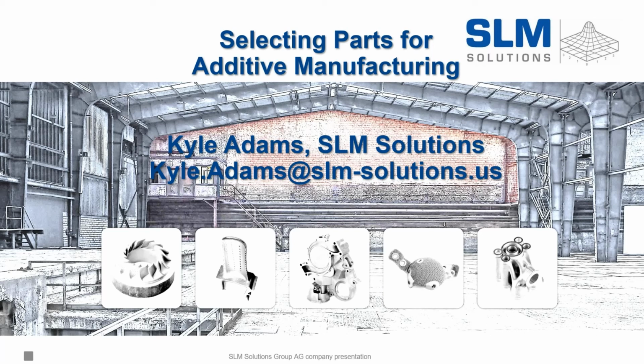forced porosity is put in to break up grain structures, and then hipping is used to close up any of those porosities after the part is made, making a stronger piece. So sometimes hipping is used as a tool to create even stronger metal with on-purpose porosity. But after hipping, everything should be 99.9 and above density.